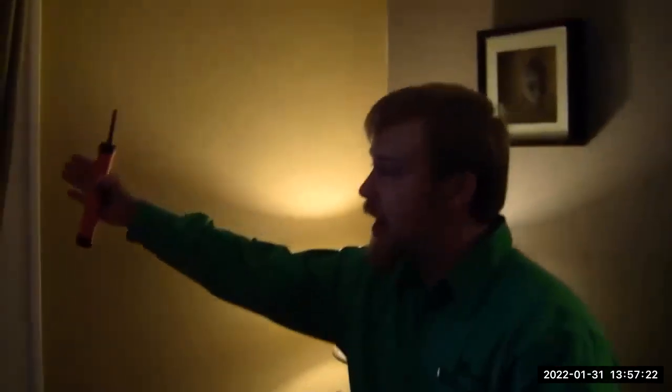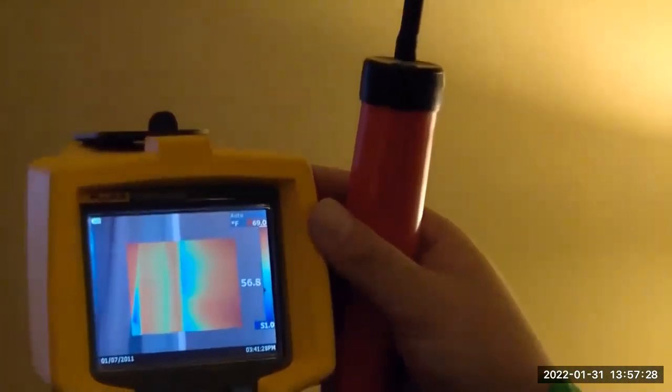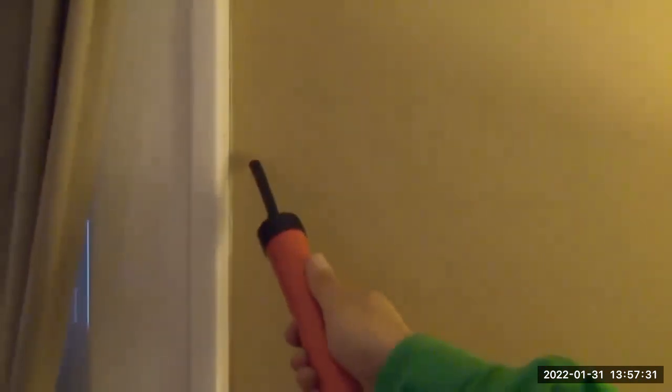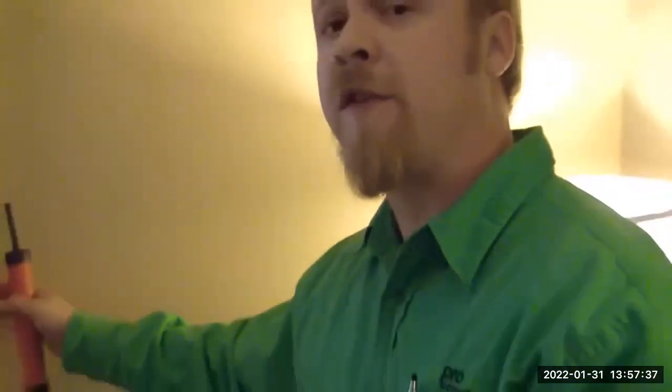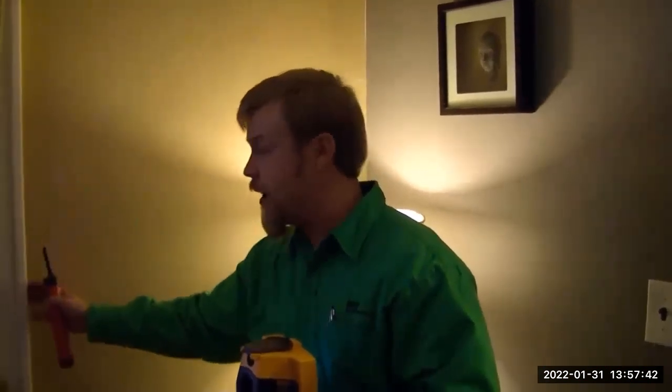The thing is, like this particular customer, they just had new windows installed. And a lot of times what you find is people don't need new windows. That's what I'm finding here: they actually have a lot of air leakage around the windows themselves. When I shoot it with my infrared, I can see the cold air coming in. And then we use our smoke pencil to where you can see all that air is blowing that smoke away. This is a simple repair versus actually just replacing your windows. You can shoot the caulk to seal that on up.